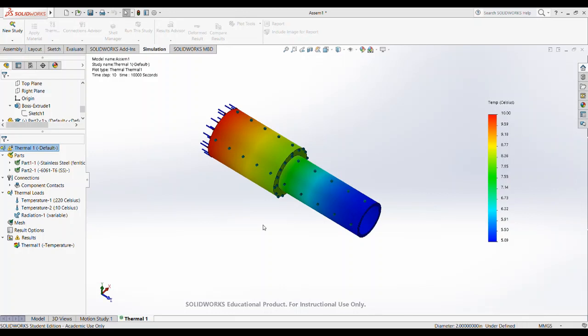What you might want to do is select another probe point. You might want to select a warmer one, because you want to ensure the whole thing reaches 20. So you might want to select the probe point that is on the warmer side instead of in the middle, to assure that the whole cat bed is under 20 degrees. Or you might want to select a point out here somewhere, right? Even though I had mentioned it's the cat bed part, the part that's in here that you want.